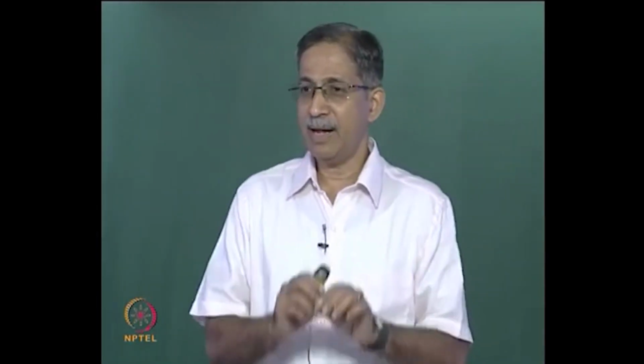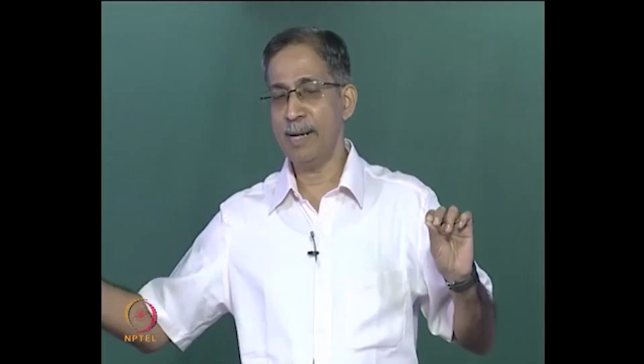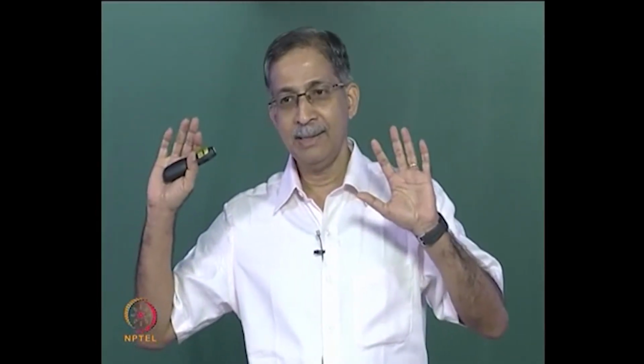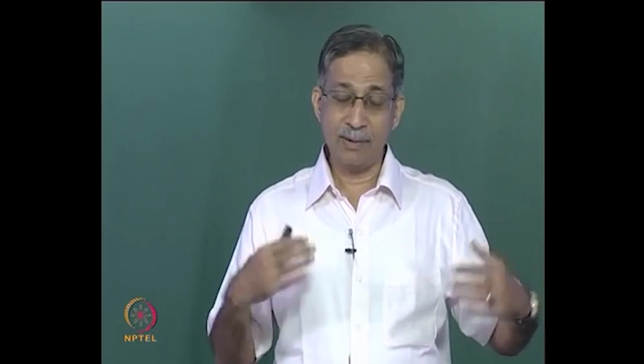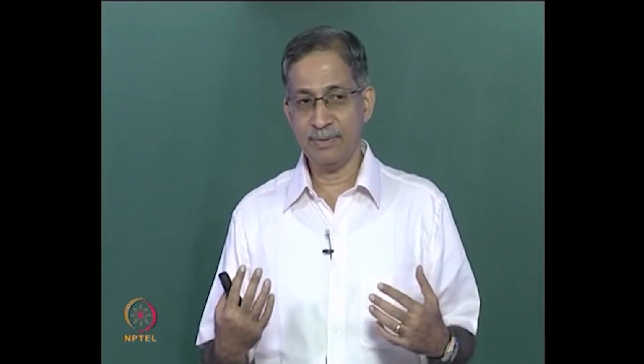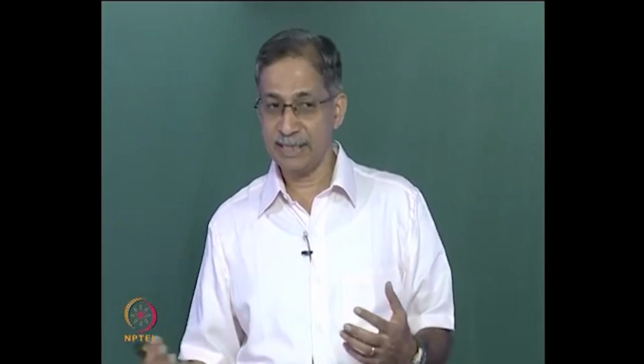What's our objective? We are trying to find a solution to a problem where we can deal with only joint loads. So we have to convert these into, we want to find the net load vector, and also we want to find the fixed end forces which accumulate at the restraint coordinates.